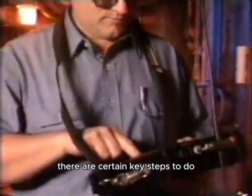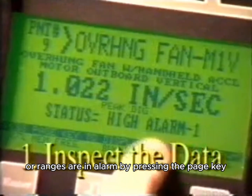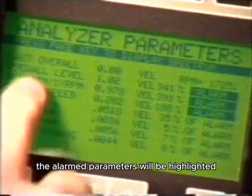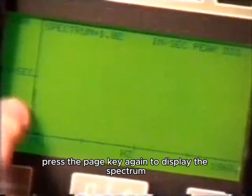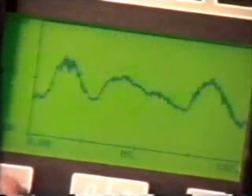There are certain key steps to do when an alarm is triggered. First, determine which frequency range or ranges are in alarm by pressing the page key and view the listing of the parameters. The alarmed parameters will be highlighted. Press the page key again to display the spectrum and make note of the frequency ranges that alarmed. View the waveform to confirm any possible preliminary diagnosis.